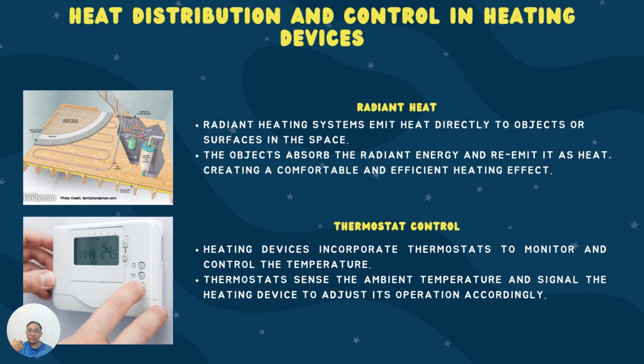So, if the actual temperature falls below the set temperature, the thermostat signals the heating device to increase the heat output. Conversely, if the actual temperature exceeds the set temperature, the thermostat signals the device to decrease heat output or turn off. This mechanism ensures that the heating device operates efficiently and maintains the desired comfort level. Advanced thermostats may offer additional features such as scheduling, remote control, and energy saving mode.